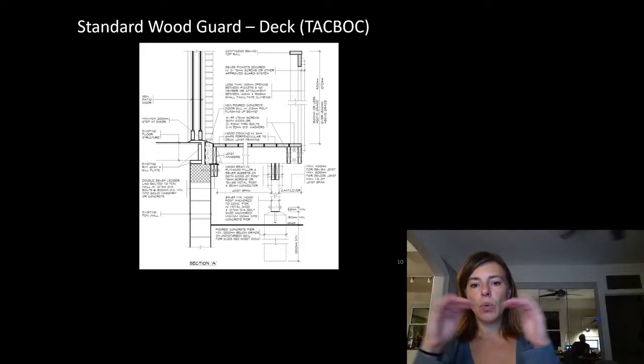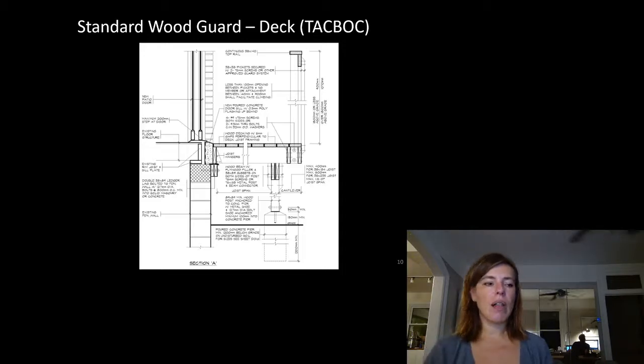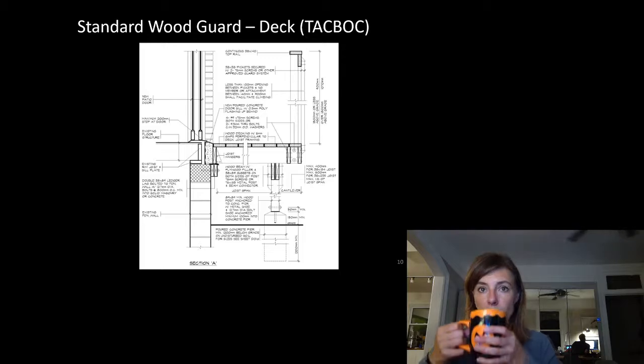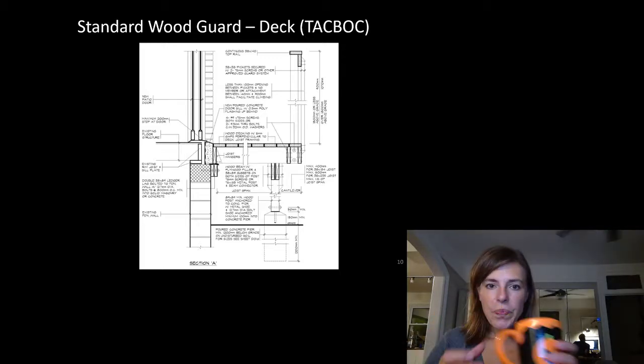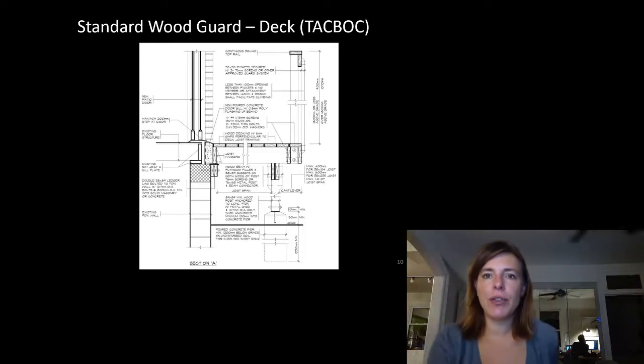If we had no top rail, if a glass panel failed, you have nothing to prevent that opening at the top. Glass guards, we've seen incidences in Toronto where glass guards have spontaneously failed on some of the high-rise condos. So if you didn't have a top rail, you'd have the possibility of somebody being able to fall off there with absolutely no protection whatsoever. I'm thinking of all of these things now that I'm talking about it that I want to add into these slides for you guys.